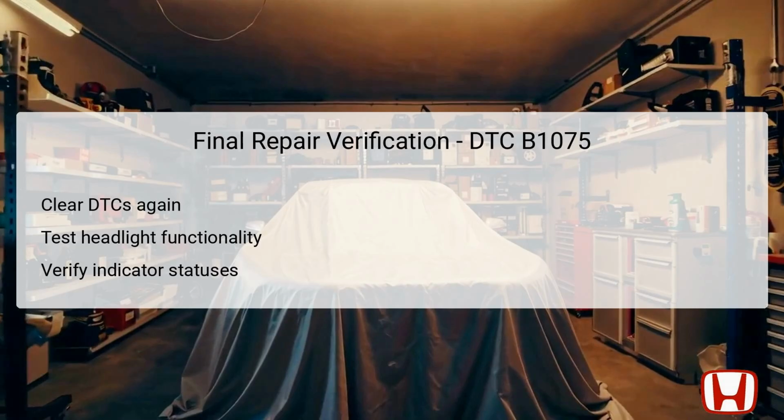Start by clearing the DTCs once more using the HDS to ensure the system's memory is reset. Following this, conduct a comprehensive test of the headlight functionality to see if all modes, off, parking, and on, are operational as expected. It's equally important to monitor the indicator statuses on the dashboard during this phase.